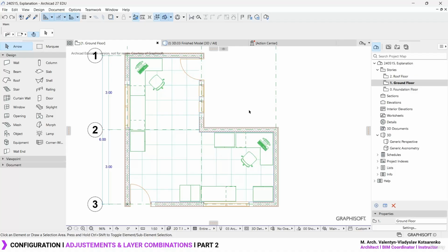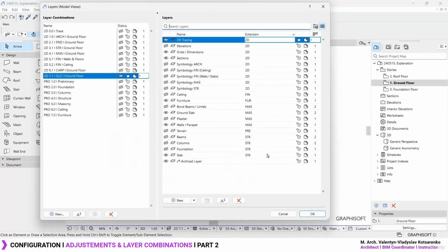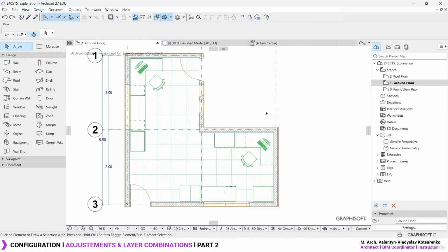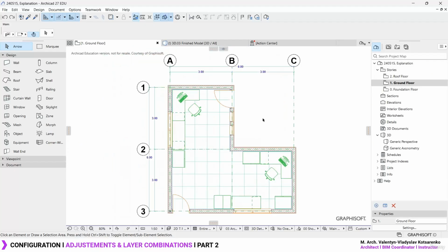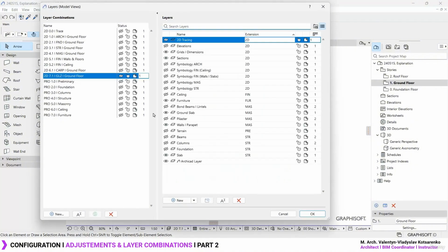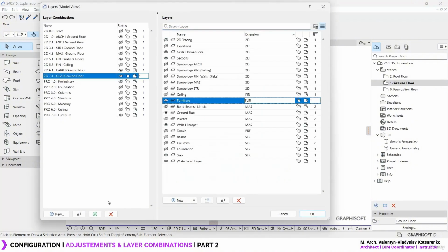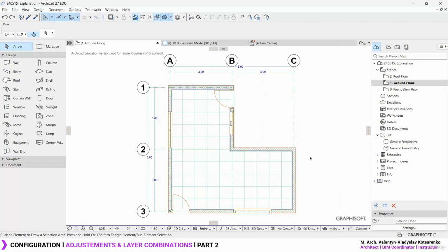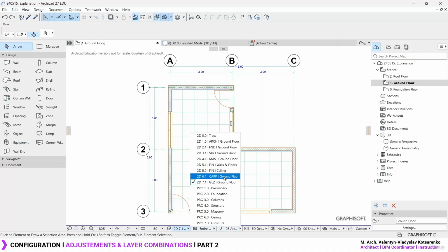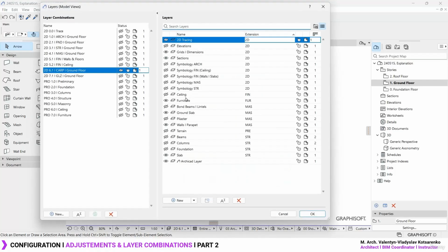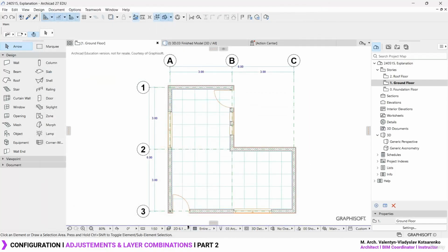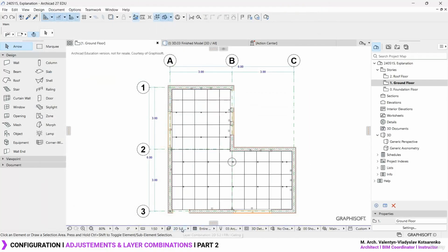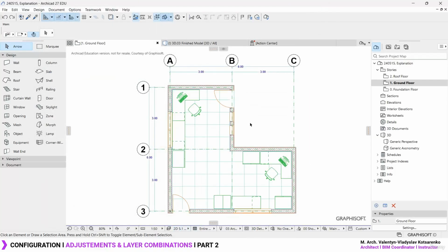Okay, well, the glazing, we're still going to fix this real quick. Press OK, and now the pilasters are also set. Well, for the glazing, I definitely also recommend deactivating the furniture and updating this so it stays something as basic as it is. The same will go for the carpentry. Maybe also deactivate the furniture, update the layer combination, and now, yeah, pretty much we can say we are almost set.